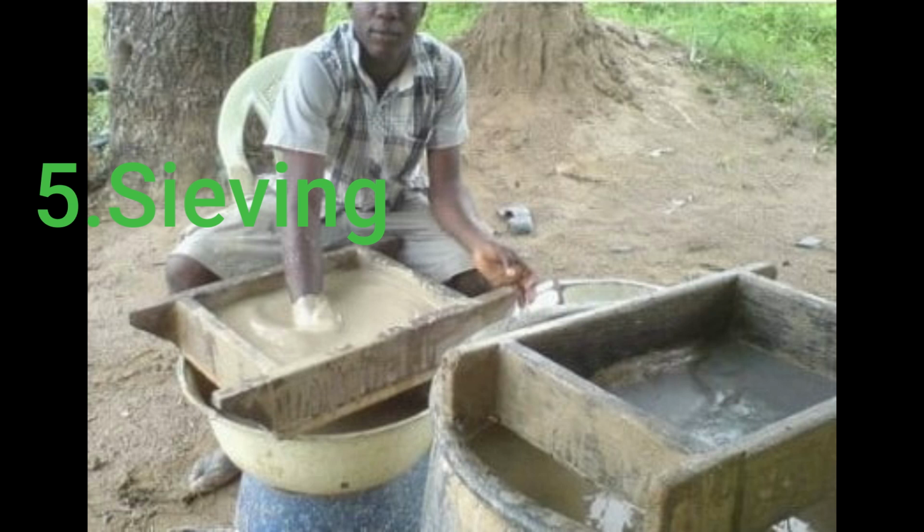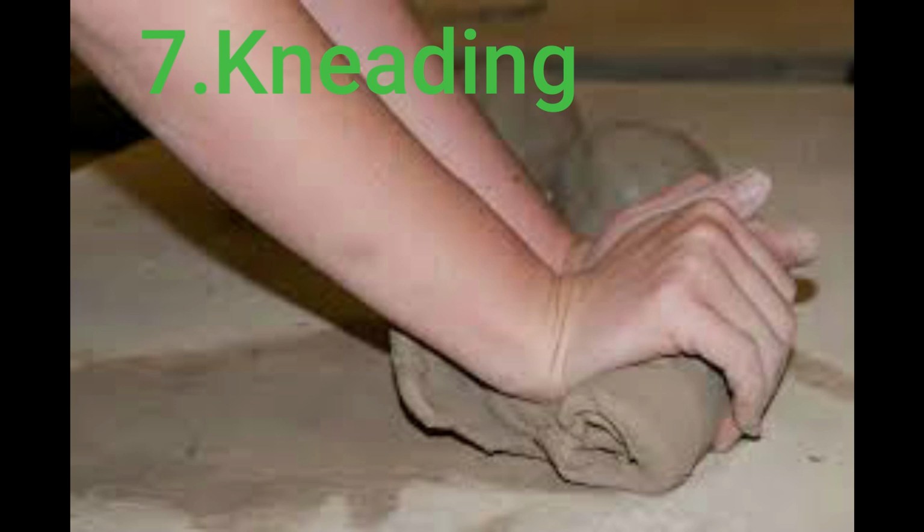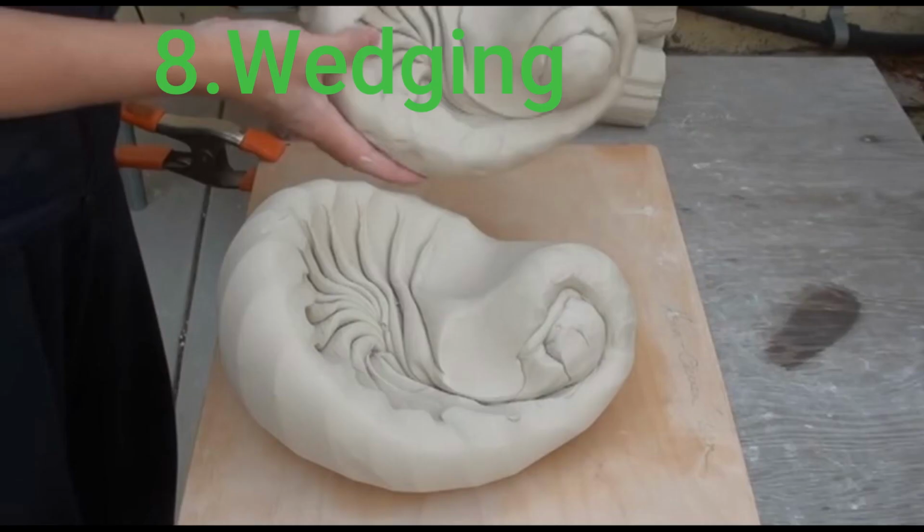Sieving is then done after mixing, and it is done with a wire mesh to remove more particles or impurities. Hardening is the other step, and it is done by placing the clay on an absorbent surface like plaster of Paris so that it loses excess moisture. Kneading is the other step, and this is the blending of clay to a homogeneous state by pressing the clay forward and backward on a flat surface by hand. Wedging clay is kneading clay further to expel any air bubbles trapped under it.